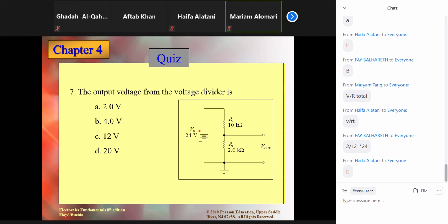See, by the way, this time it is not a variable resistor. You can see there is no arrow. Sometimes for a variable resistor, an arrow is shown like that. It shows variable, but it is not. It's a fixed resistor. Its value is given, which is 2 kilo ohm. So the output is fixed this time. Output will not change. It will always be 4.